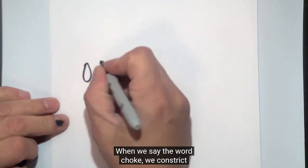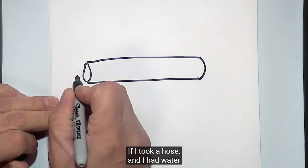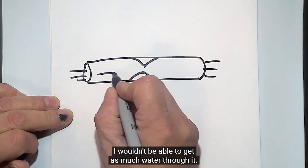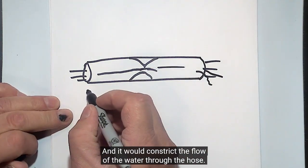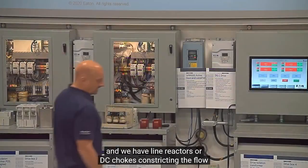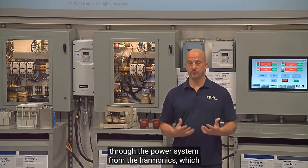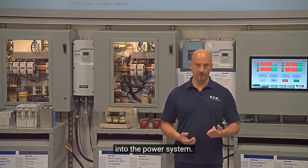When we say the word choke, we constrict the flow of harmonic currents or high frequencies. If I took a hose and I had water flowing through this hose and I constricted the flow or pinched this hose, I wouldn't be able to get as much water through it. And it would constrict the flow of the water through the hose. So in a similar way, if we have conductors in the power system and we have line reactors or DC chokes constricting the flow through the power system from the harmonics, which are high frequencies, we're not going to allow as much high frequencies to come out of the drives and flow back into the power system.